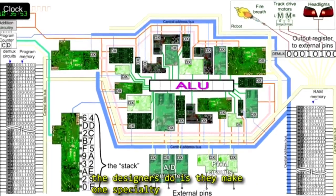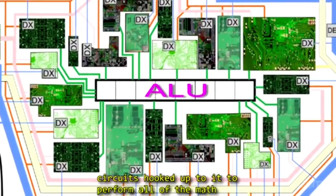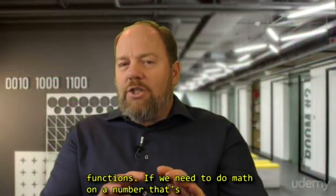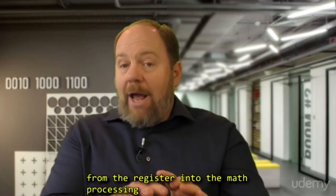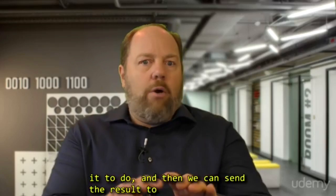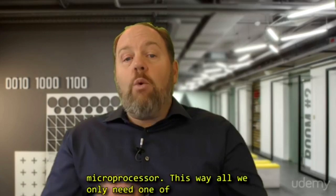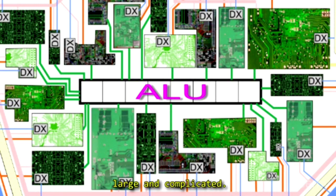Rather, what the designers do is they make one specialty register, which has all of these complex digital circuits hooked up to it to perform all of the math functions. If we need to do math on a number that's stored in a register somewhere, we load that number from the register into the math processing register, do whatever mathematical function we want it to do, and then we can send the result to wherever, back into the register from whence it came, or some other destination in the microprocessor. This way, we only need one of all of those utility circuits that are so large and complicated.